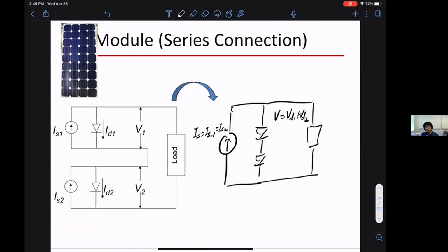But then of course, if you have partial shading, part of the module is covered by a cloud or the shadow of a tree, and part of it is not. Then they're not equal. One has fundamentally more current than the other. The question is, what do you do when this happens? Often you're limited by the least amount of current you can pull.